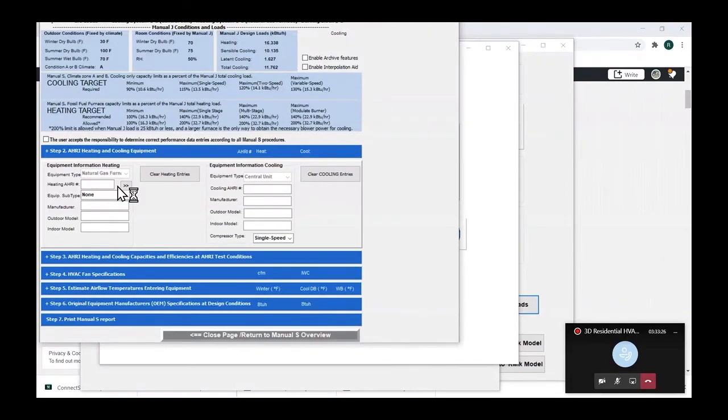And so if you look at that load count and you use the exact same equipment at every project you do, you're an HVAC contractor, you always buy a certain type of equipment, a certain brand, a certain series of equipment, and you see that load calc number, you go, that's a 2.5 ton. I've done a dozen of these. Then you can type that number right in here. You can type in your AHRI certificate numbers, your efficiencies, and all that other stuff.